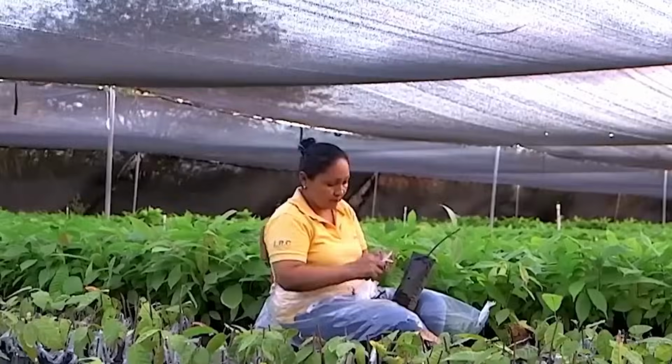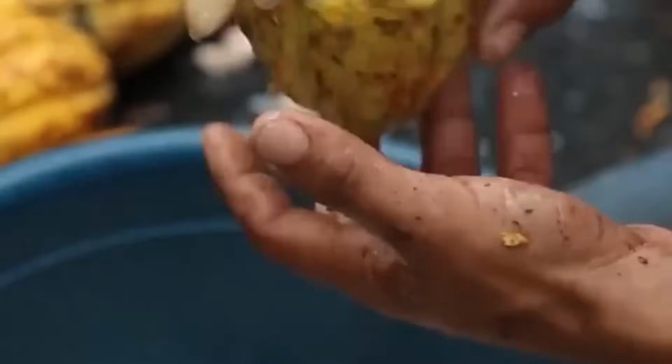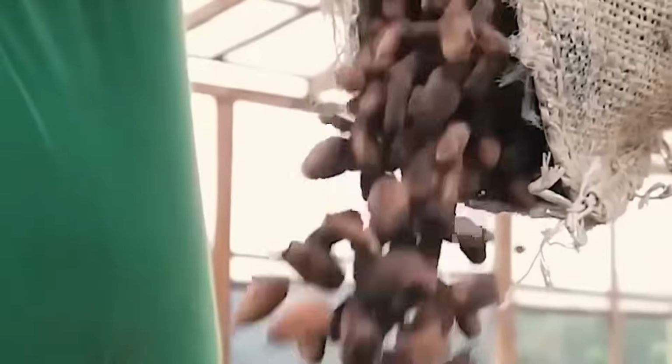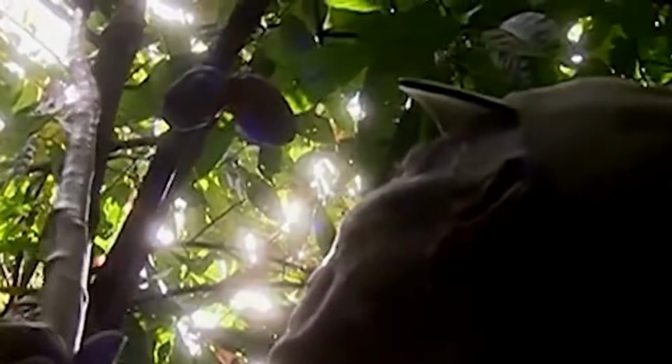The initial applications are made with higher syrup content to ensure adhesion and are followed by increasingly dry applications to harden the shell. Between each application, cold air is blown into the pan to crystallize the syrup and lock the layer in place. The coating is built in 20 to 40 layers, with rotation speed, syrup flow rate, and airflow rate adjusted in real time by PLC-controlled systems.